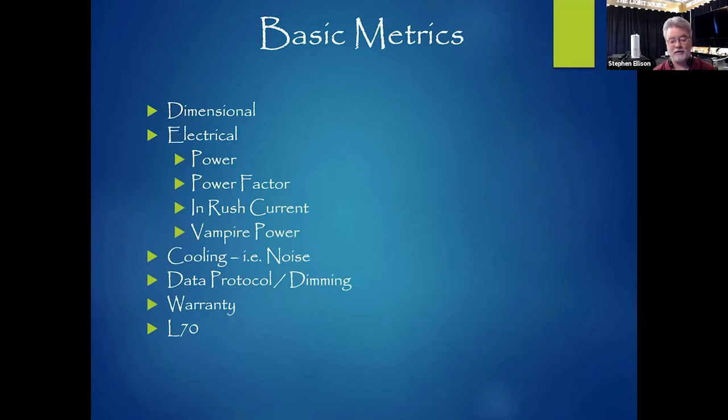And something to think about is if you've got to power up that circuit card first before it actually outputs light, meaning it listens to the DMX input and tells the LEDs to turn on, well, what's the first thing it's got to do? It's got to figure out what's happening. So it's got to power up the central processing unit, meaning every LED fixture basically has a little computer in it because it's listening to DMX, and DMX is a digital language. Digital meaning you've got to have a computer to interpret what is coming across the line.